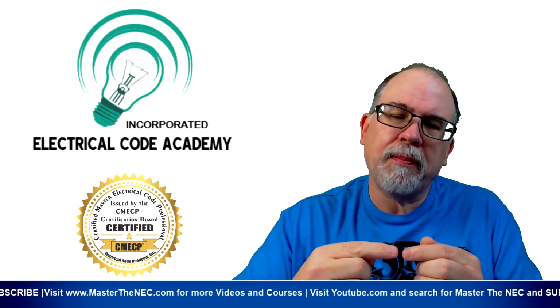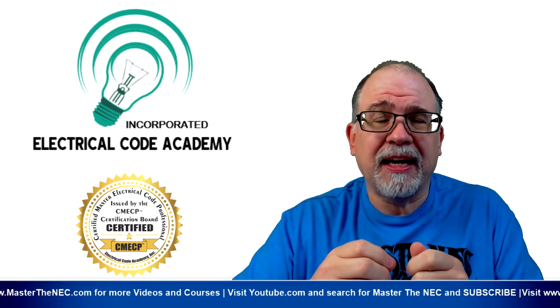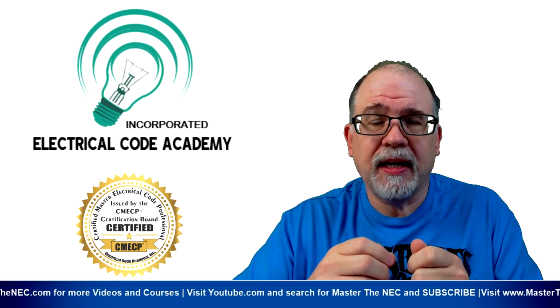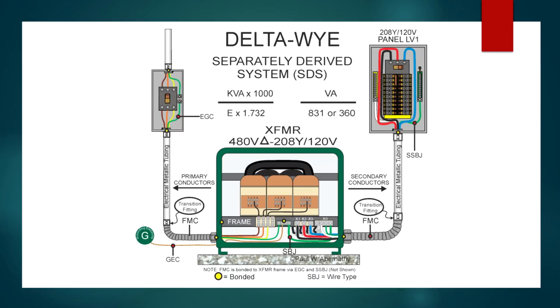So in our application, we had a 480-volt primary line voltage. Okay, so if you go back to the graphic and look at the presentation, we're going to take the 75 kVA times 1,000. That's going to give us 75,000 VA. So over here you see I've simplified it.